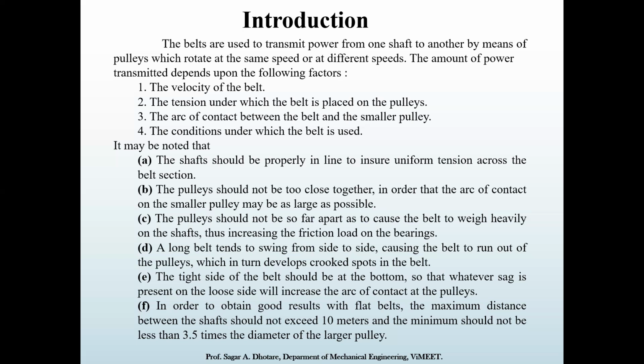Next one, the long belt tends to swing from side to side, causing the belt to run off the pulleys, which in turn develops a crack spot in the belt. So as I said, as the distance is too high, the belt starts bending.